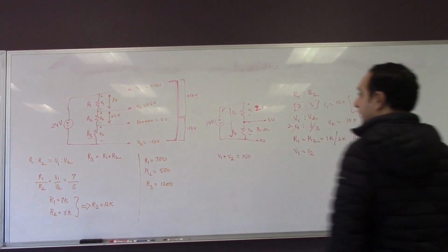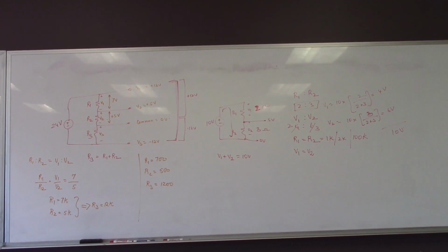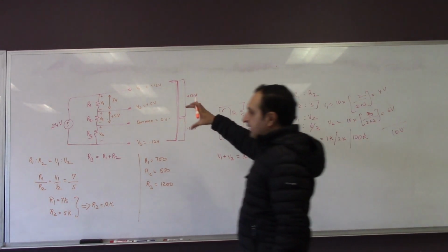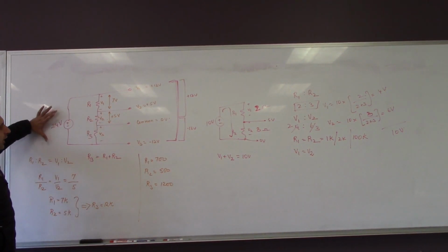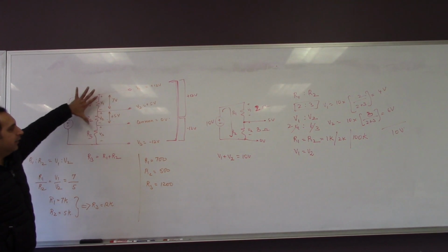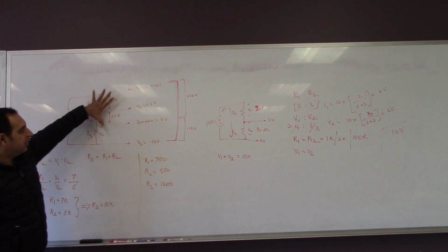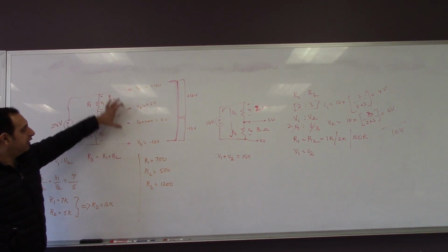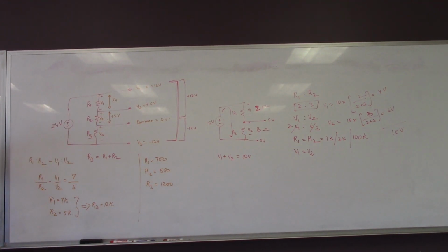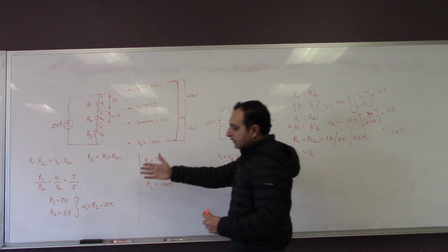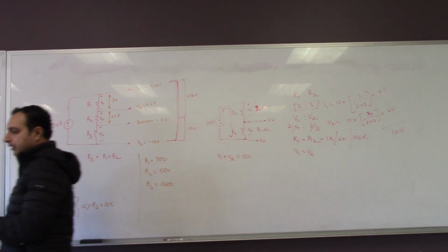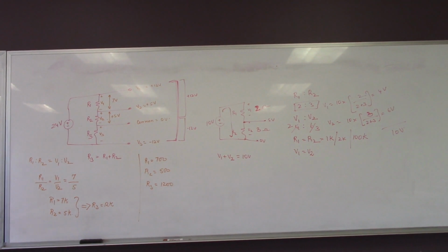So the idea here is, if you are given a circuit where you're trying to design a voltage divider, it takes 24 volts and it divides it depending upon what your output requirements are. If you want 5 volts, negative 12, plus 12, and so on, just take them in the similar ratio. Any one of these answers is fine so long as you keep the same ratio. You can multiply that by 100, 1,000, whatever you like.